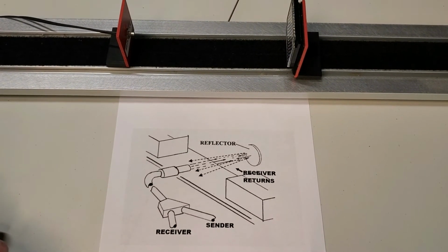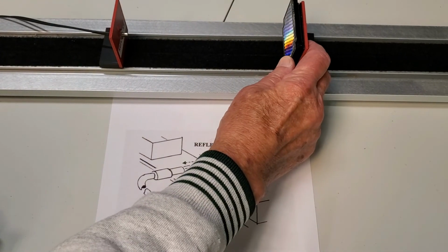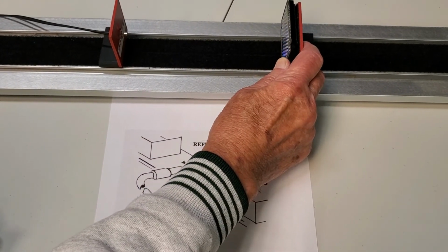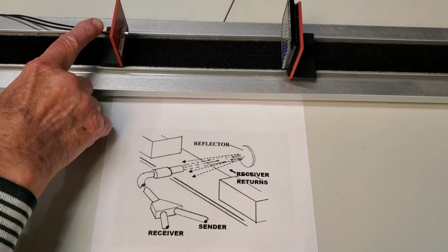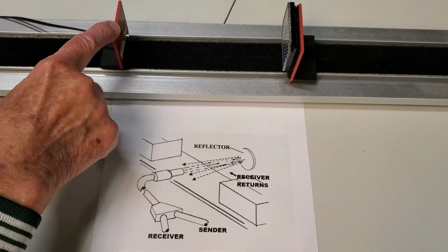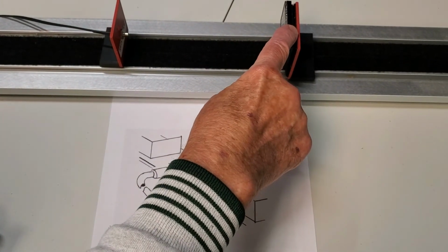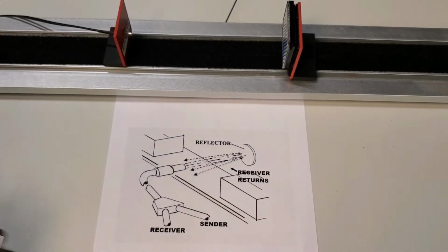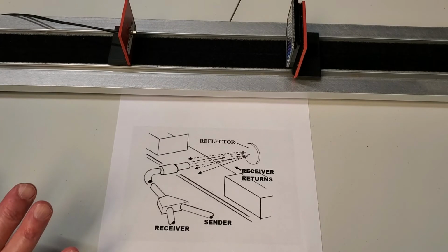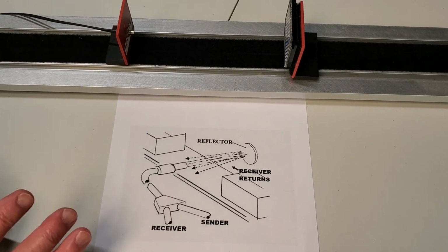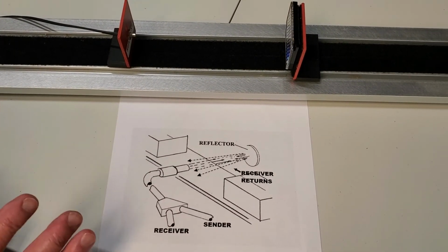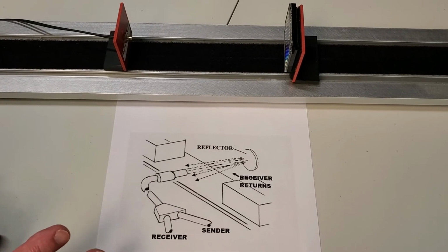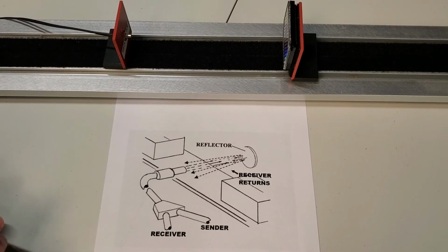It's referred to as retro because we're using here a reflector, industrial reflector, with a reflective lens. So it's basically sending out one signal to this, and it's receiving back approximately 1,000 returns. So the advantage of this is used in automation, especially by places like UPS, to say that when only certain packages pass through, will you push them off the line.